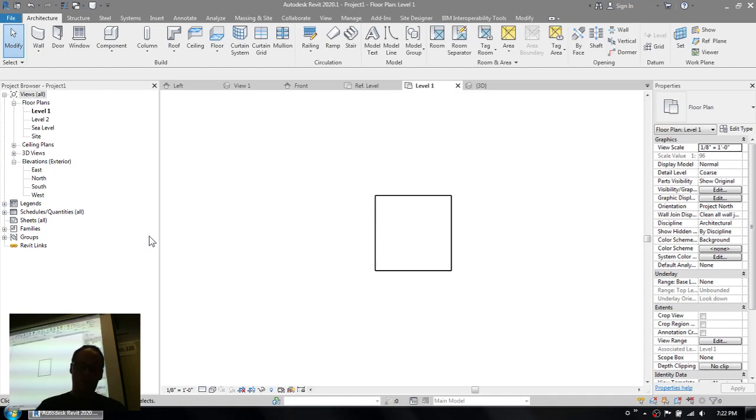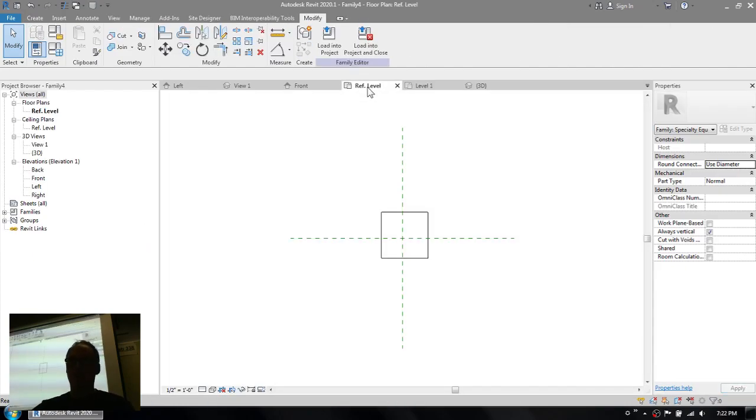And this is by default. So if you want to show your lower cabinets as being cut by the plan cut plane, you can choose that yes option inside the family. So again here folks, just keep your eyes on the screen. I'm going to change this thing again.